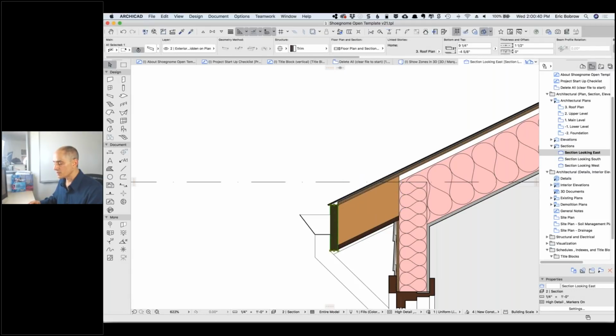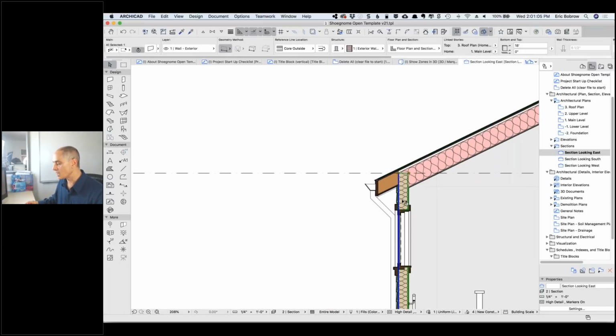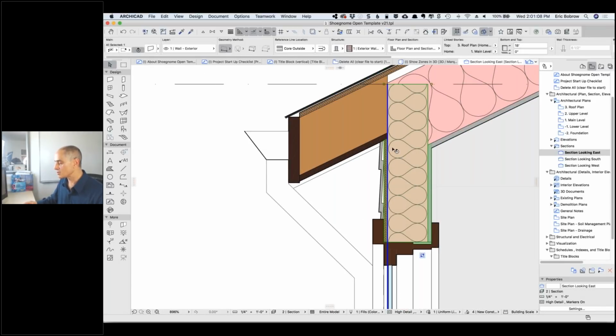And then look here, what you may not notice is that this thin cover is an upper roof. So it says roof finish. So he basically has a main roof inside, a cover that extends over the whole top, and then he has an outer piece here and some additional pieces, you know, for covering the edges up. If we go to the wall type, we have this. Now, if I zoom in on the wall type, you notice that what's highlighted here is the structural wall and the interior cladding.